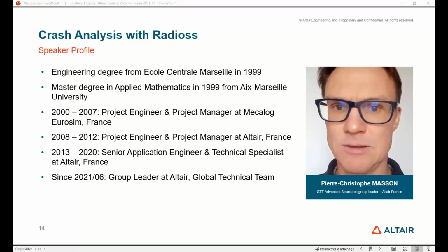ALE and Eulerian formulation, as I showed also in the fluid and structure interaction application, will be more adapted for fluid modeling, of course, such as the fluid in a tank, or whatever other fluid, but it can also be the air, for example.